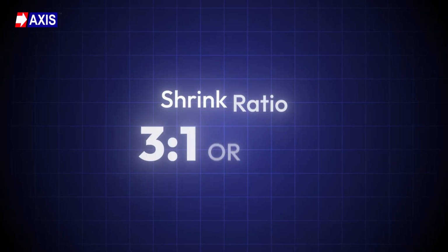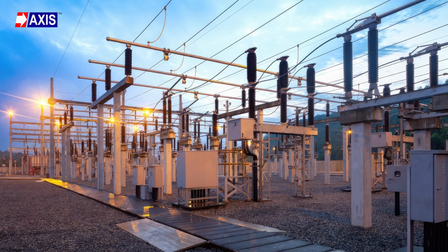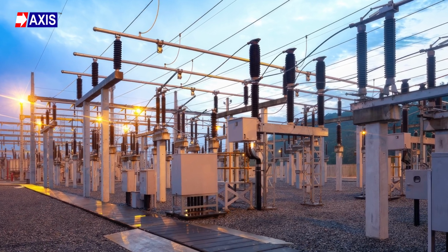That's where 3:1 or 4:1 comes in. These ratios are designed for irregular shapes, thicker connectors, and uneven joints. They allow the tubing to stretch over larger parts and then shrink down tightly to seal thinner sections. In high-demand environments, even 4:1 might not be enough. That's where 6:1 is used. It handles extreme variations in diameter, like thick cable lugs paired with smaller conductors. You will find this ratio in high-voltage insulation.